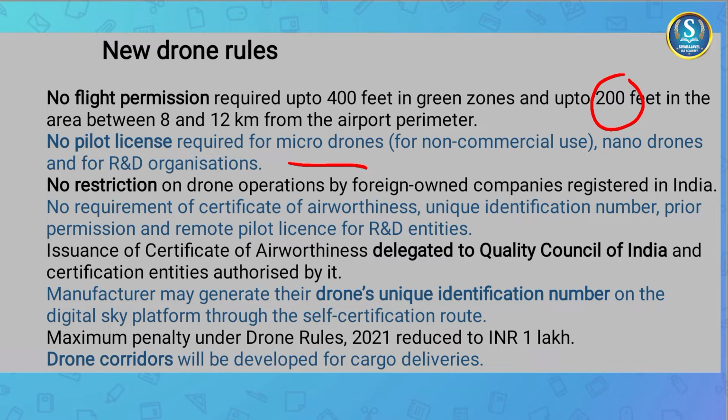And there is no restriction on drone operations by foreign-owned companies registered in India. You have to note specifically that it could be a foreign-owned company, but it has to be registered in India, else they might face some restrictions. And there is no requirement of a certificate of airworthiness, a unique identification number, prior permission and remote pilot license for R&D entities. Only for R&D entities are these things not needed.